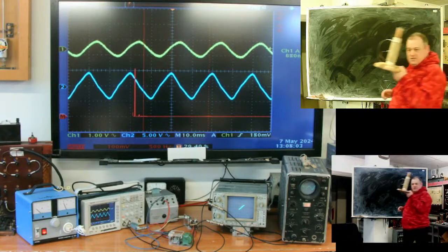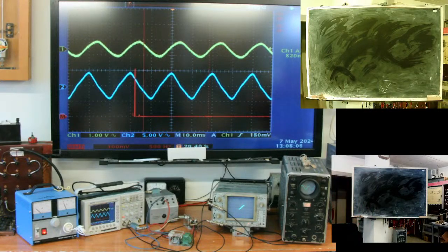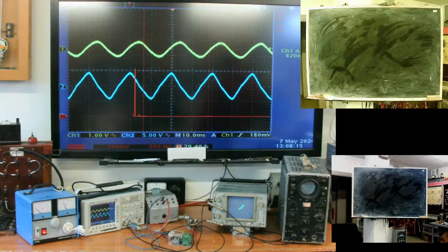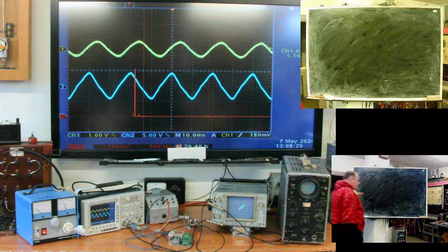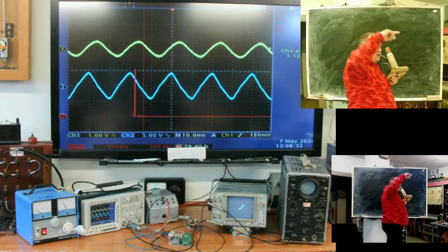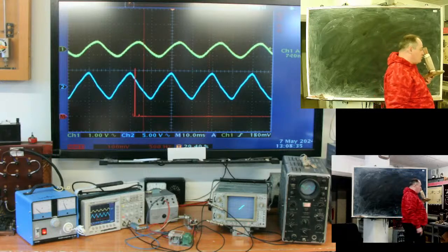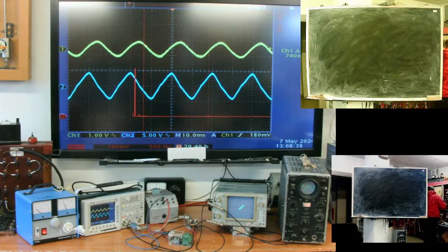This is an air transformer. It has no problem with linearity. The problem is with efficiency. It's very ineffective because it has high magnetic resistance. This transformer is much more effective, but it has a steel core. And when you do something with ferromagnetics, they are all non-linear. They all have this loop of magnetizing. Nothing is ideal.